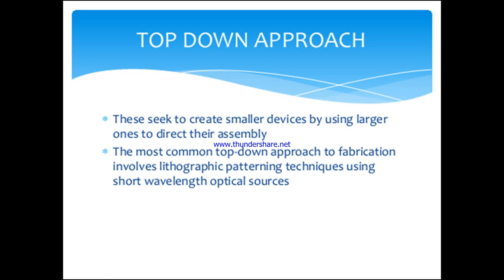In this we are going to have macroscopic materials. Macroscopic, that is a huge material, can be converted into the nanostructured in an extremely controlled process here. So for example, we are having ball milling technique, or it may be etching through the mask, or else it is an application of severe plastic deformation.